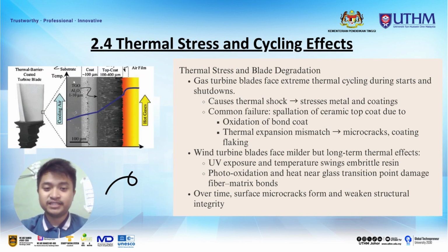Gas turbine blades face extreme thermal cycling during starts and shutdowns. This causes thermal shock, which stresses the metal and coatings. Common failures: spallation of the ceramic top coat due to oxidization of the bond coat, and thermal expansion mismatch leading to micro cracks in the coating,